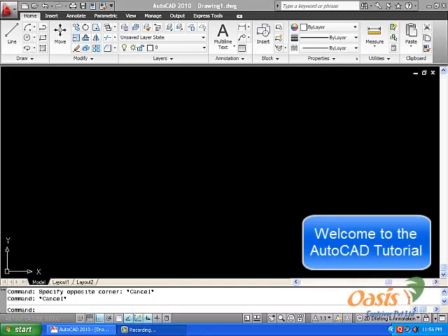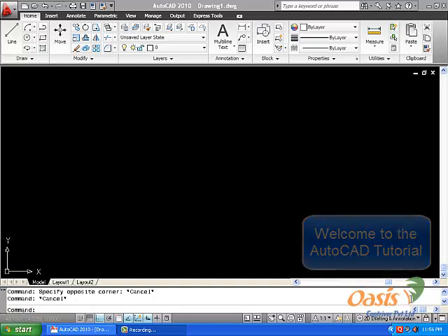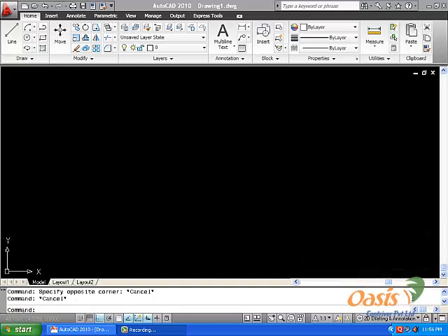Welcome to the AutoCAD tutorial part 3. Here we will learn the rest of the tools of Draw. In Draw, we have learned line, circle and rectangle. Now we will learn the next tool, which is known as ellipse.